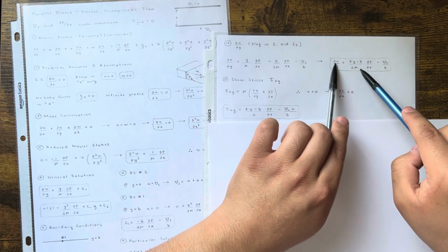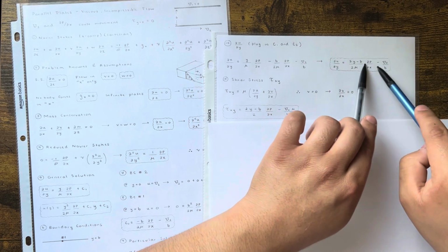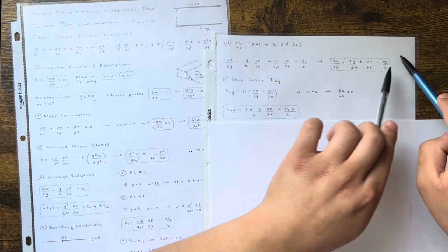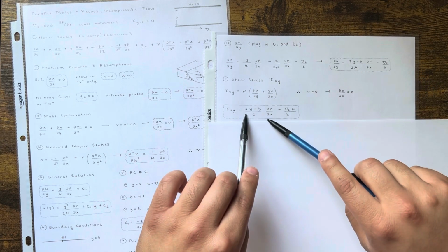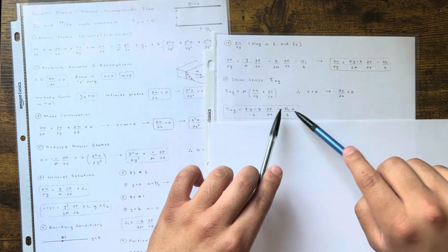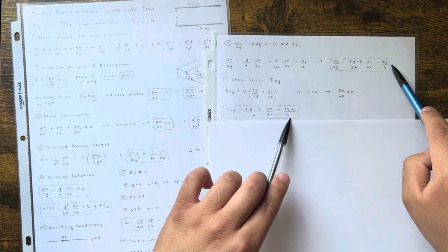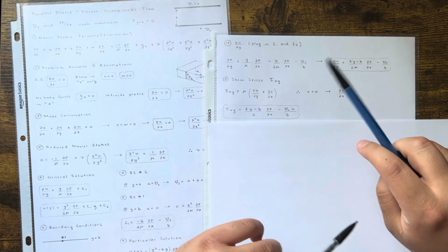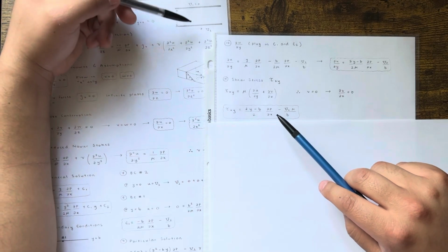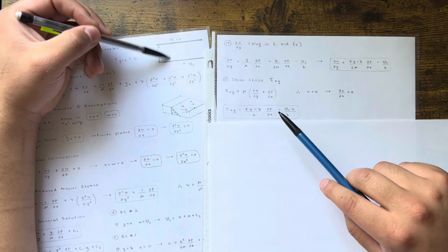Well, we already have this. So it's just all of this times mu, right? So that mu is going to go away, and you're going to add a mu over here. So that's what I did here. 2y minus b over 2, delta p over delta x, minus u2 mu over b. So now that I have tau xy, this tau xy tells me the shear stress anywhere along the distance between the two plates.